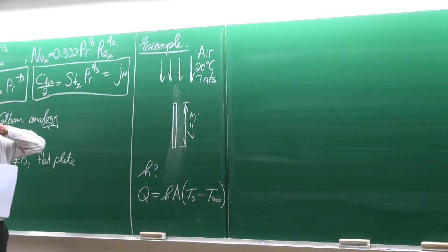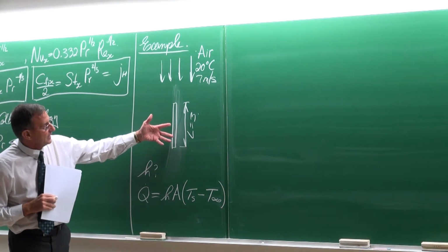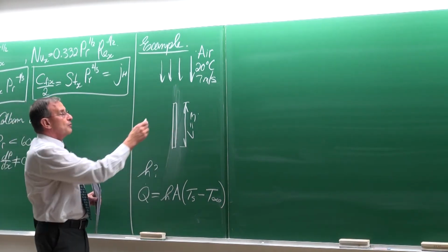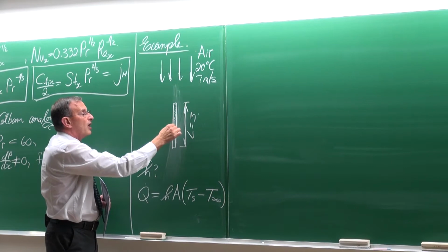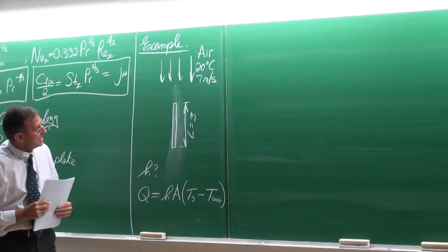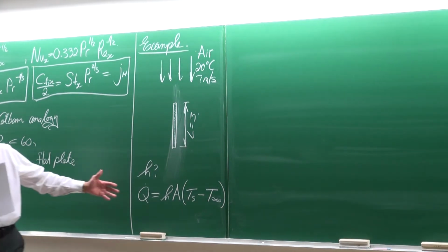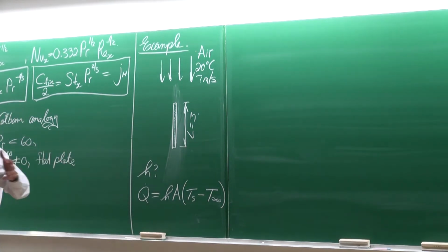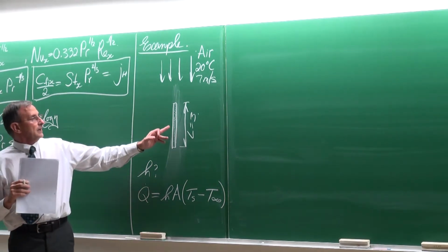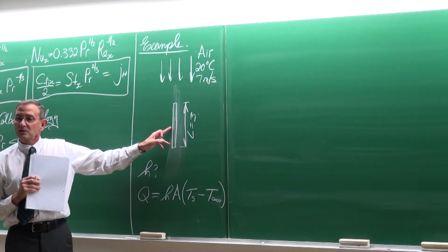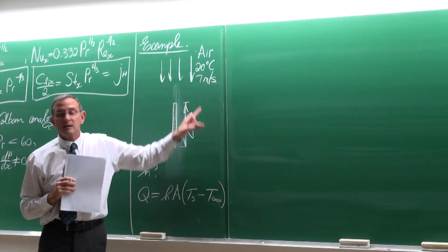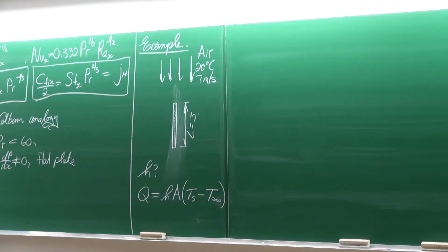And then you would think of this plate and you would say, right, how can I get some heat transfer in it? So most probably I will put in an electrical wire there or an electrical resistance element, and I would put a heat flux through it, which I can measure, the voltage drop and the amperes, so that I can get this term. I can go and measure the fluid temperature, the surface temperature, and that temperature is 20. And then I can get the heat transfer coefficient. You agree? So that is typically an experiment that can be done.